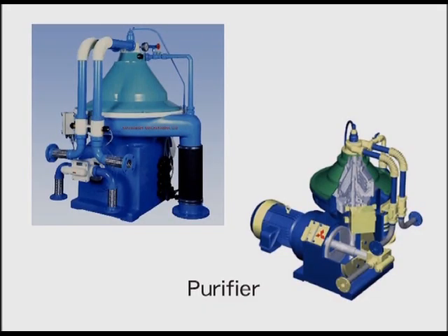First, I will explain the typical cleaning procedure for lube oil system in the vessel. Select the purifier based on gravity board selection procedure described in the Operation Manual of Purifier. The appropriate interval for discharging the sludge varies with the quantity of the mixed-in insoluble content, so adjust the interval for discharging after having checked the degree of dirt of the bowl.